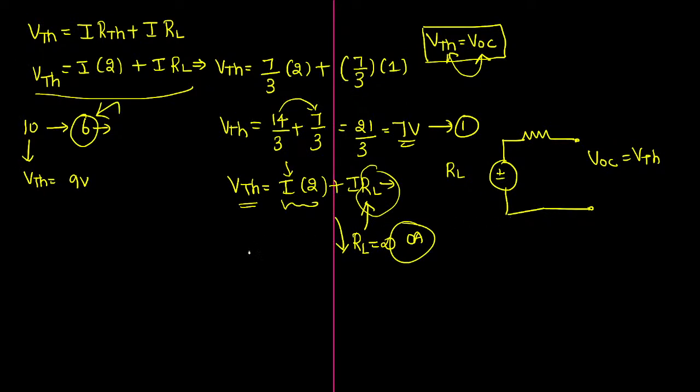See, when they are connecting the 8 voltage source, they have not connected any load resistance at the output port. When there is no load resistance, then simply the output voltage will become equal to the supply voltage that they are connecting. So it is very simple to identify the answer. That's all. So the correct answer is going to be 8 voltage. I hope you all understand this. Okay, chalo. So this is how we are solving.